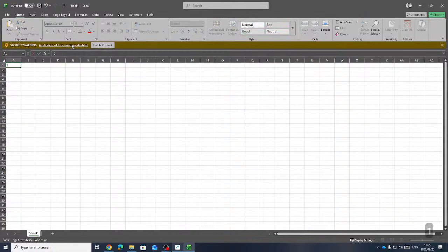Okay, so very easy. Can anyone guess why we're going to use a 170 course? Just a wild guess. It's got to do with, you walk up them a lot in this building. Stairs. Okay, we're going to make working out stairs a little easier. So 170, it's 2 brick courses, 85, 85, 170. But the going and riser, that's a standard going and riser for a stair, 170 by 280 or 250. So we thought that the structural might work better with the circulation, because your circulation has to work with the differentiation between different types.